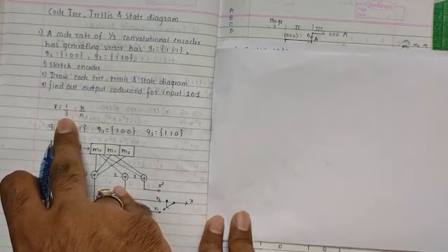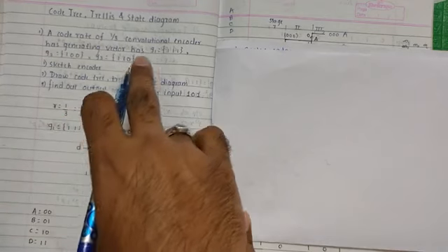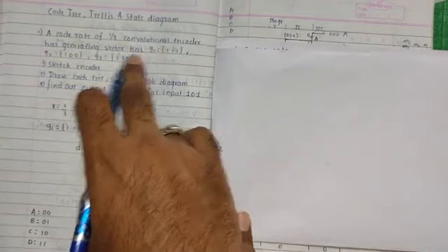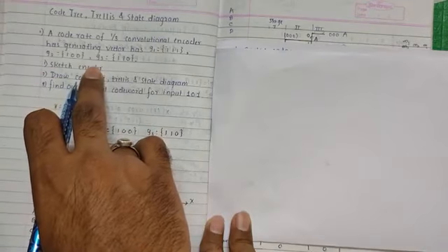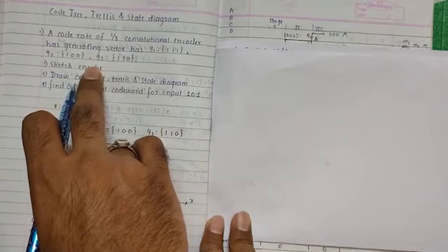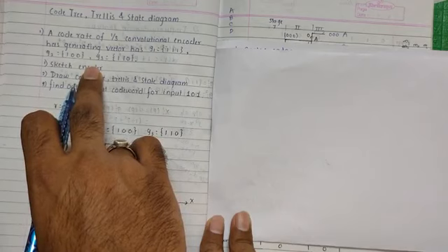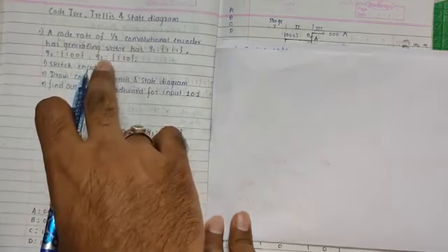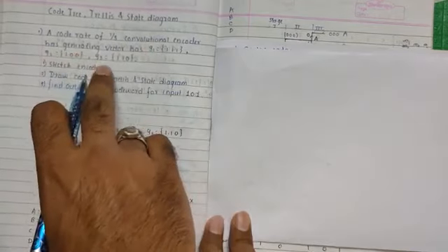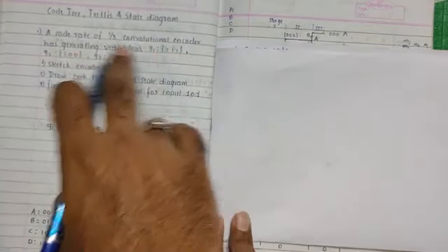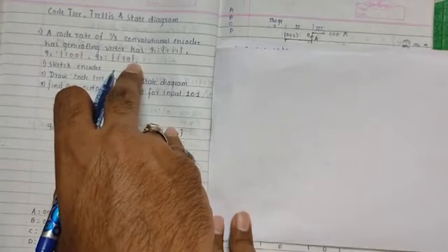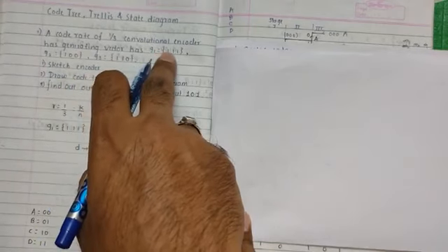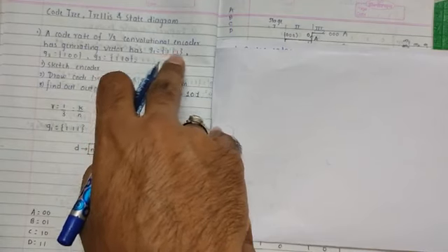Now let us try to draw the encoder here. From the given impulse responses G1, G2 and G3, how many responses are mentioned? 3. It means we need to draw 3 XOR gates in the convolutional encoder, one for each of G1, G2, G3. And in every response how many bits are given? 3. It means there are a total of 3 shift registers, as they show the connections from the shift registers.